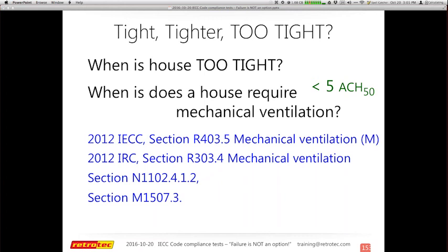All right. So if the exhaust fan is not there, that could be kind of a challenge because sometimes their dampers don't open and close so easily, or they're already open all the time. But if the dryer is not located, you're not allowed to cover the dryer opening. You're actually determining if the damper on the outside is being pulled tight when you do the blower door test. That's why we're depressurizing. All the dampers should be pulled tight and determine what my test is.